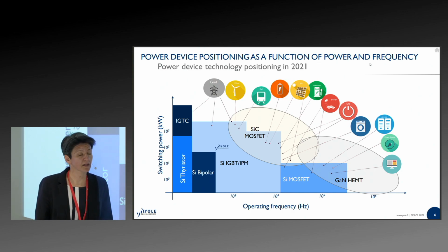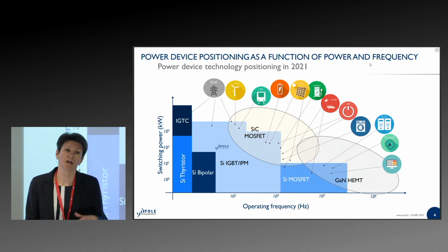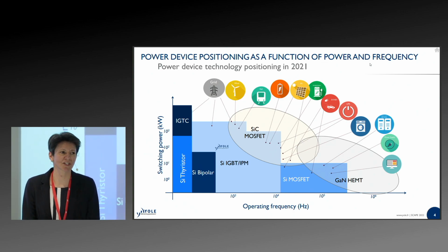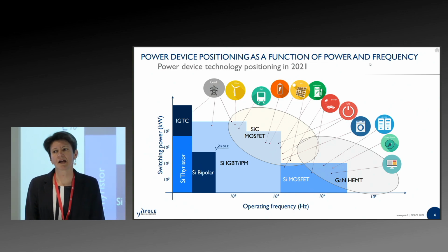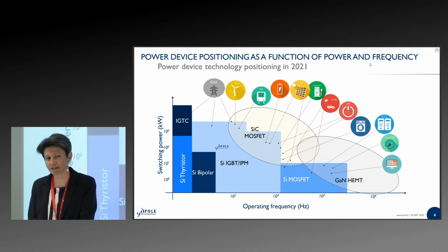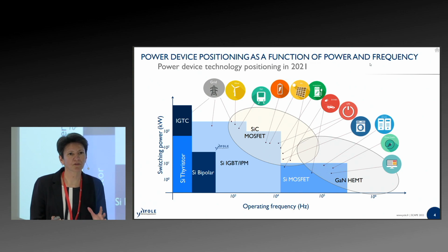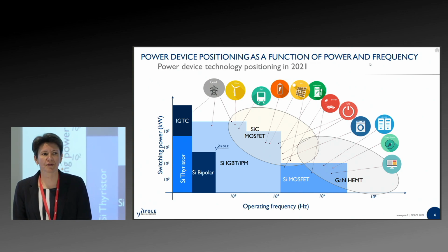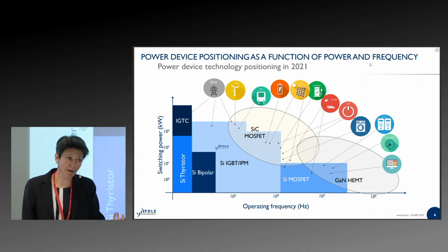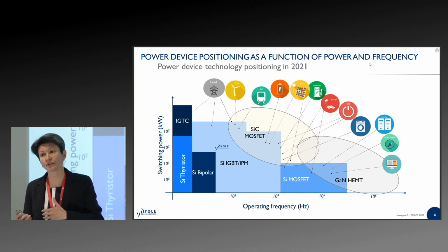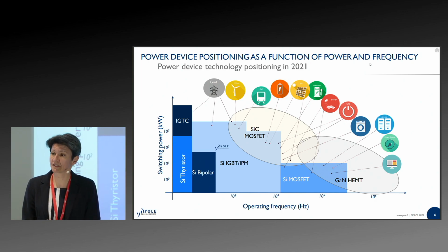So we've heard some discussions on the bipolar thyristor. We didn't hear that much about the more mature technologies for these high power needs. Today, players are looking at IGBTs or MOSFETs. A simple way of putting this together: we say IGBTs are very much inclined to address the high power levels, while the MOSFETs, junction MOSFETs, are very good in tackling these higher operating frequencies.